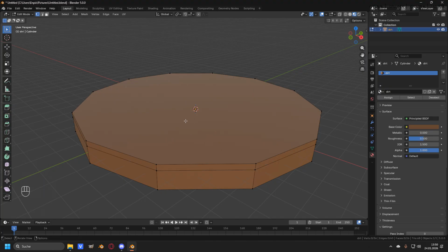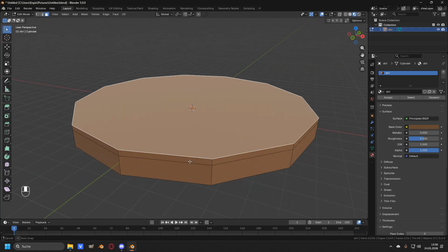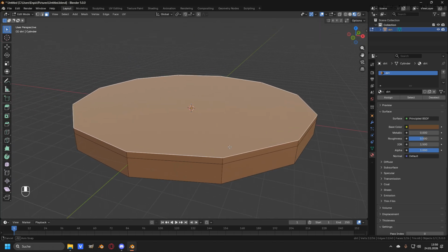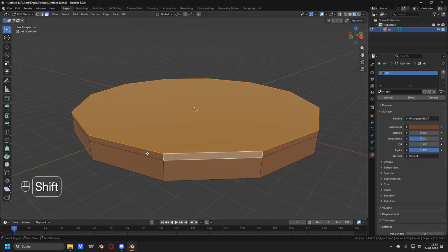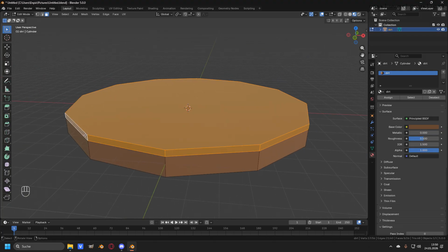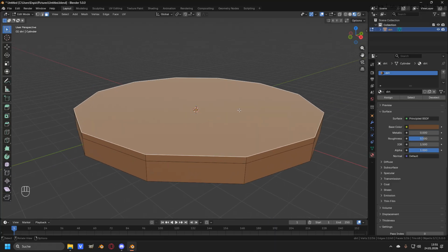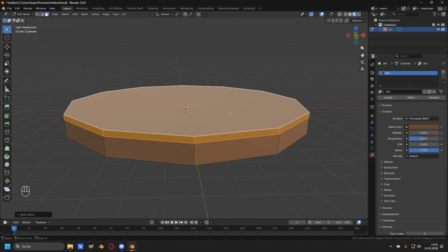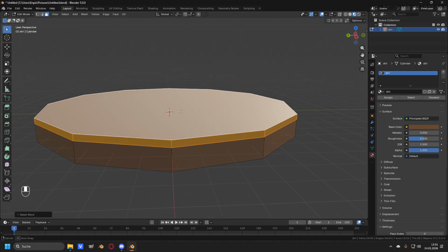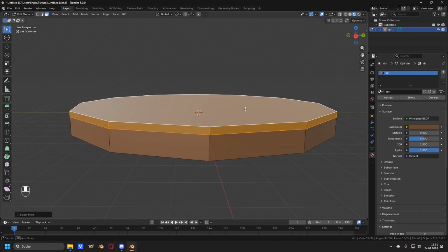Now let's select all of the faces that we want to have in the grass object. For the face selection, press 3, and at the top left right here you can see that we're in the face selection mode. Then select this face right here, and now we need to select all of these faces around the cylinder. You of course could press Shift and just manually select all of these faces right here. But there's actually a very easy way to do this, because if you have selected the upper face right here, you could just hold Ctrl and press numpad plus to extend the selection, and you can see that all of the faces that you wanted to select manually are already selected like this.